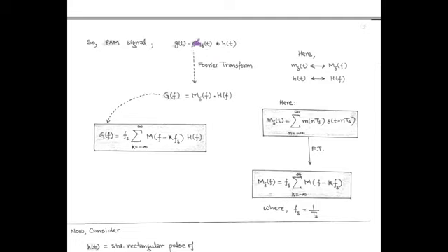So, in time domain, PAM signal is denoted by g(t), and it is equal to the convolution of m_δ(t) and h(t). And we know that the Fourier transform of convolution of two signals is simply the multiplication of their individual Fourier transforms. And here PAM signal, that is g(t), is in time domain and its frequency version is denoted by capital G(f). So G(f) is simply the multiplication of the Fourier transform of m_δ(t) and the Fourier transform of h(t), that is denoted by capital letters.